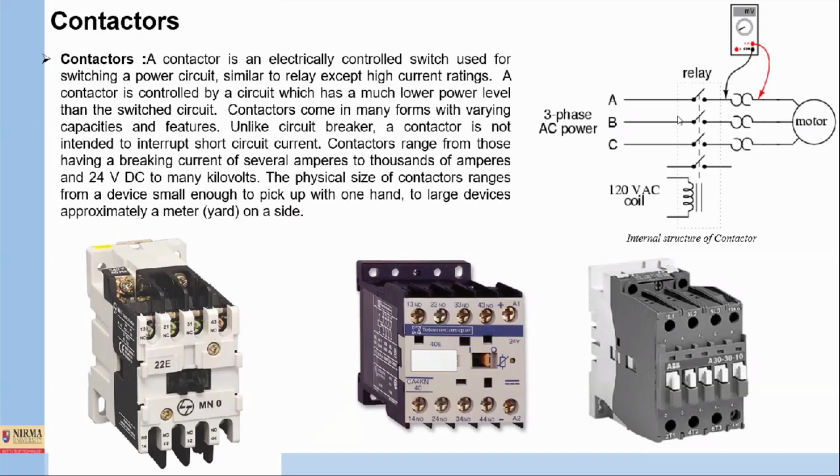Because we are going to deal with high current and high voltage, the motor may be damaged if the current is very high. So that's why we have to give protection to the line. It is costly equipment, and also the process being done by this motor is a sophisticated one. So we need some additional protection, and that's why we are supplying power through the contactor.